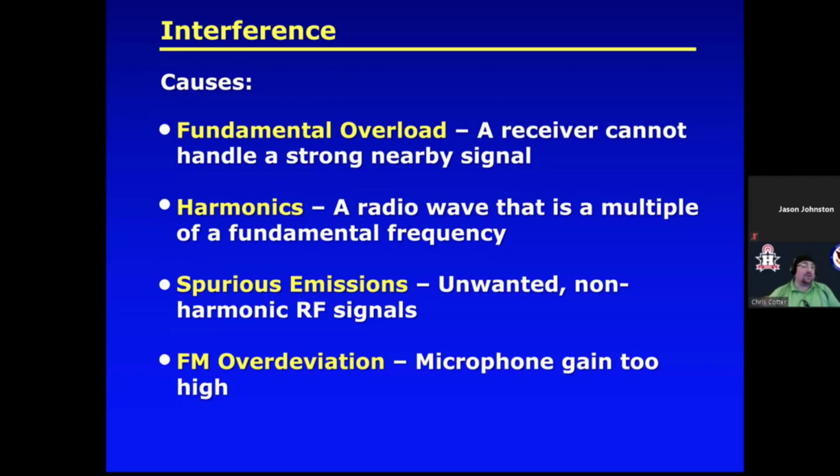Now you could keep turning your microphone gain up to the equivalent of 125%. Your radio is only capable of 100%. So what happens if you keep filling up a water bottle? Eventually, it's going to spill over, and you're going to get splatter.